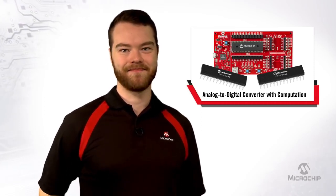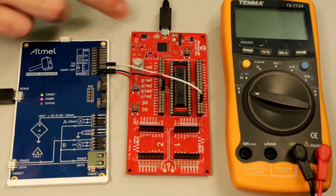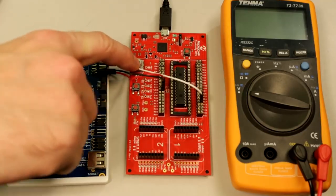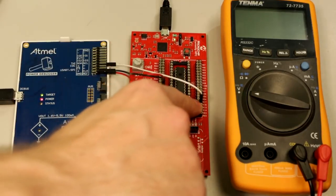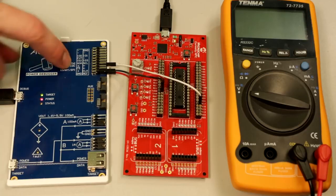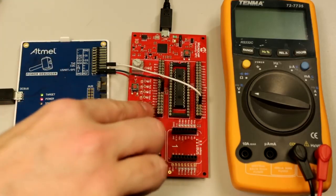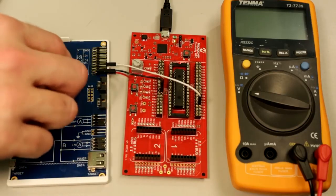So let's get started. So here we have the Curiosity HPC development board set up, and in this video we'll be using the onboard potentiometer as our analog sensor. Now this white wire here is connecting the transmit pin of the EUSART on this device to the CDC virtual COM port input pin on the Power Debugger. Then we also have a ground and VDD coming in from the device onto the ground and ref pins.